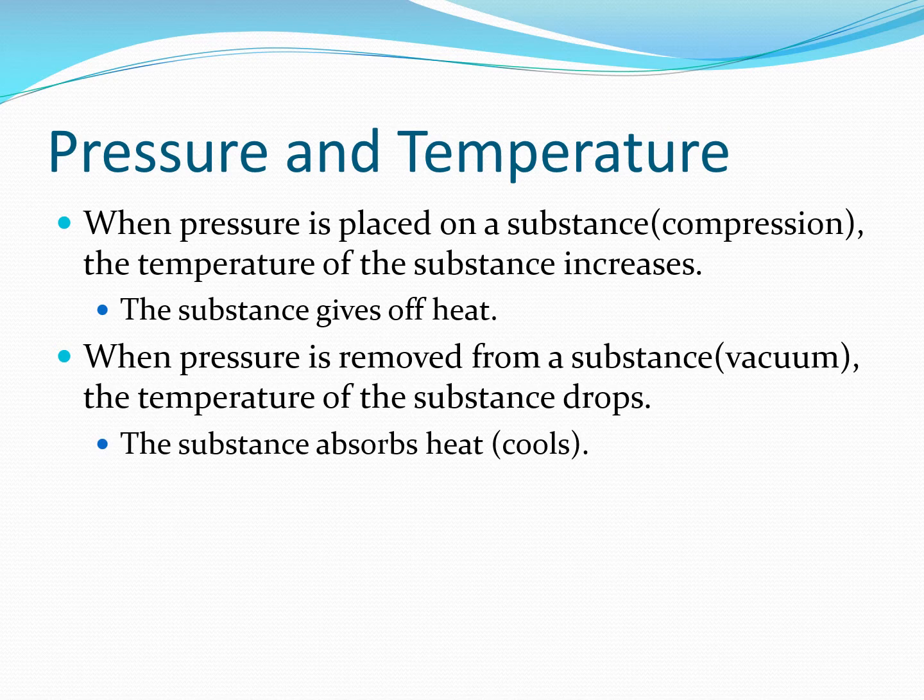So this same principle can be applied to a refrigerant system. The only difference is we're not talking about a water-based liquid. We're talking about a refrigerant that has a much lower boiling point than what we're used to. I'll get to that in a minute. I've got a chart here that I'm going to show you that shows the different boiling points for some common substances, as well as some refrigerants that we're going to be discussing, and I think it'll make a lot more sense when you see that. But when the pressure is removed from a substance, the temperature of the substance drops. The substance absorbs heat.